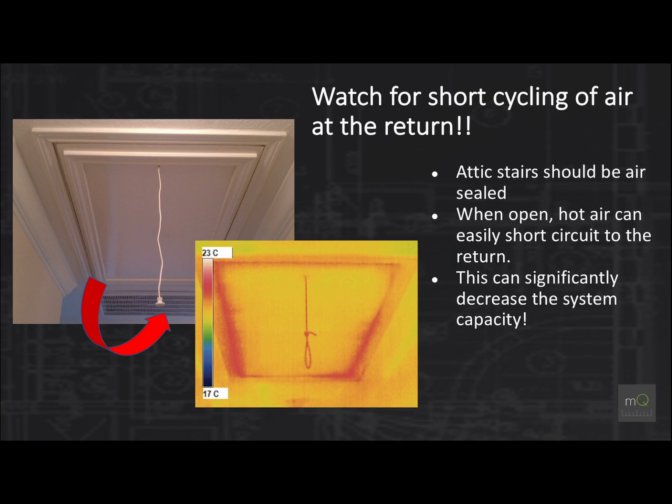So they make attic blankets and things like that. You can get in and seal these attic access holes up with them, but watch for that short cycle at the return because that will degrade the capacity of the system significantly.